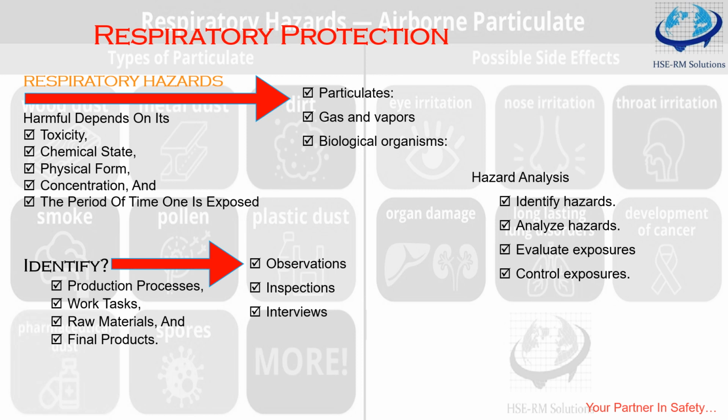Now, measure the exposure of an individual employee by sampling their breathing air. There is a breathing zone near your face up to the neck region. So that is the breathing air zone. You just need to monitor through a personal air monitor. You can start monitoring and sampling the data. This procedure is the most accurate way to evaluate exposure levels. This is the most accurate way.